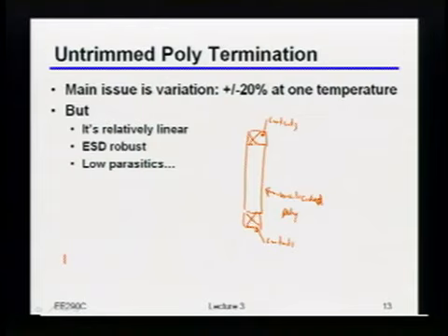What do you mean? If you want to measure a chip, your VNA or whatever is external is going to provide a 50 ohm impedance. Oh, so the question was, if I have an on-chip termination resistor, then what do you do about measurement? Actually, having the on-chip termination resistor a lot of times is better because the instrument is expecting a 50 ohm term, right? If the chip already has the 50 ohm term in it, I can just hook into that chip, whereas if I don't have the 50 ohm term, then I may get some standing waves, or some large reflections, or I may have to add an explicit resistor externally, right?